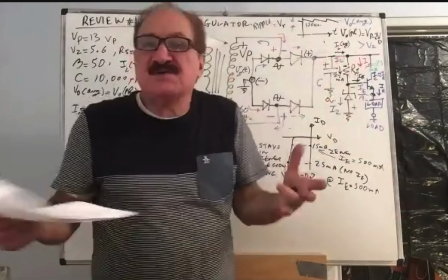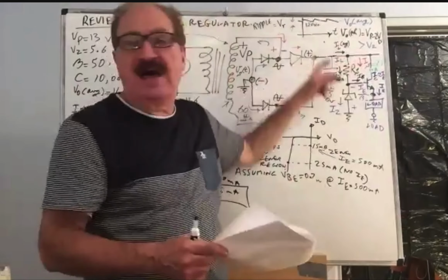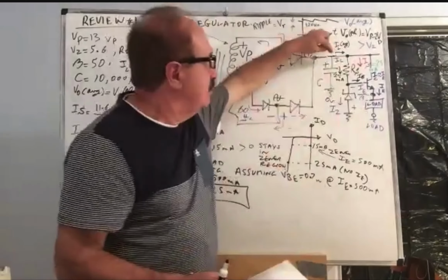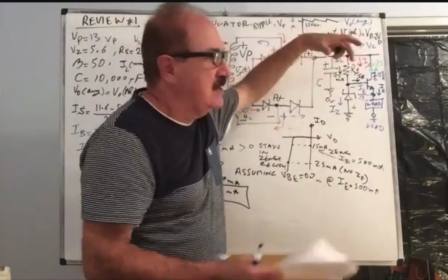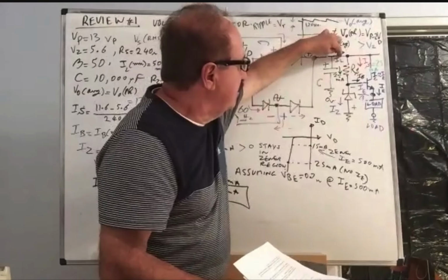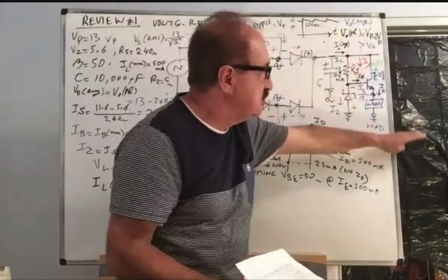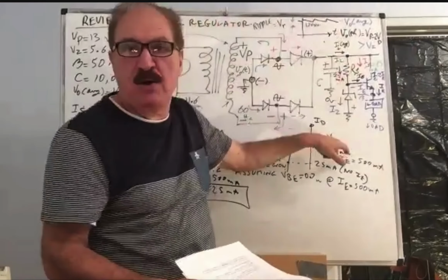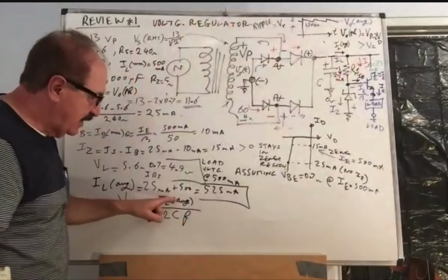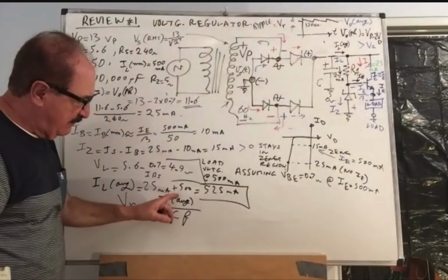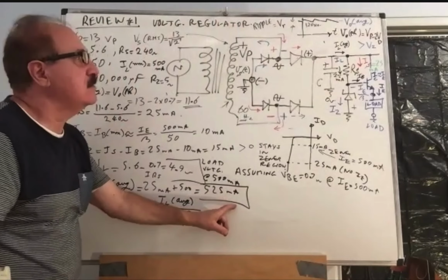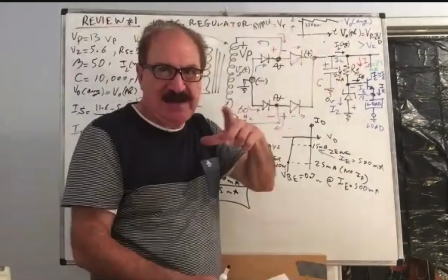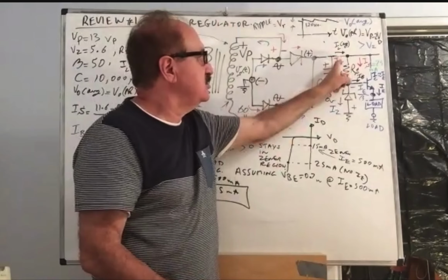But if there was a resistor, what would IL average be? Guess what? If you had a resistor R hanging from here to ground instead of that whole circuit, you would take the average voltage of the cap divided by R. So this IL could be substituted by the average voltage divided by R if you had a single resistor connected across the capacitor.